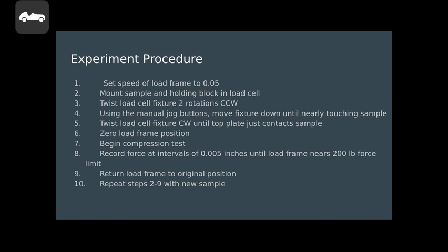After you record all the data, you return the load frame to its original position up above, and stop it there. Then you repeat steps 2 to 9 with each new sample that you have for each different infill, and just keep going until you get all the data that you need.